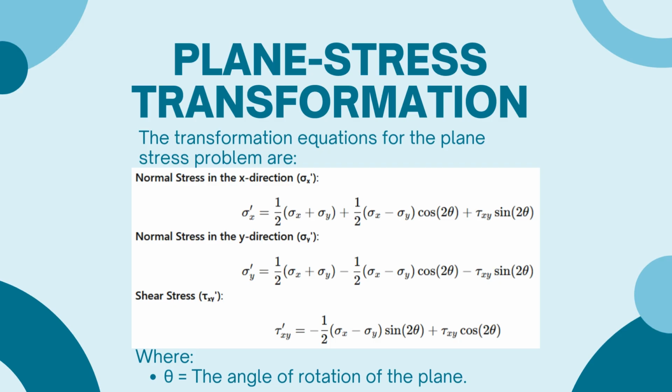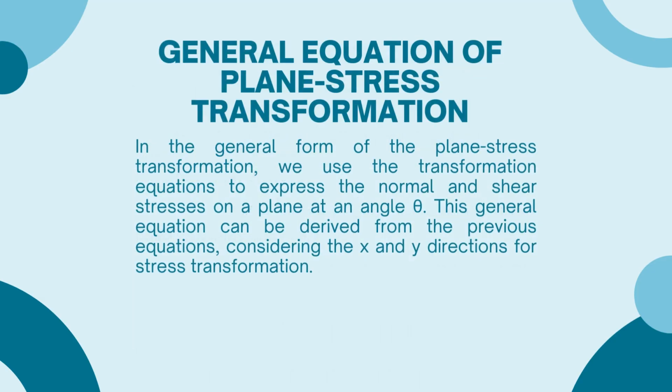The shear stress, tau, is also affected by the rotation of the plane and is calculated using this transformation, where theta represents the angle of rotation of the plane. These equations are key for transforming the stresses from one orientation to another, enabling a more detailed analysis of material behavior under different loading conditions.